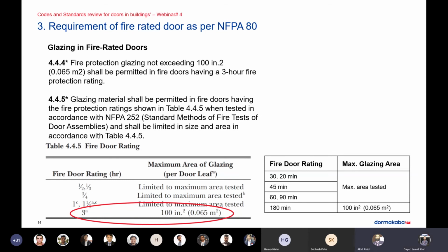Mr. Jofi is asking, are the requirements for fire rating the same for double and single doors? Yes, the code will tell us that the door in this position needs to be 60-minute fire rated. So now if you have a door, a single door or a double door or a window or any other opening here, it needs to conform to that requirement.